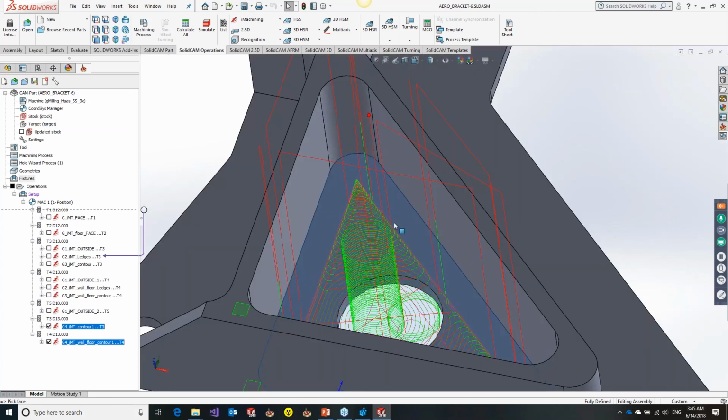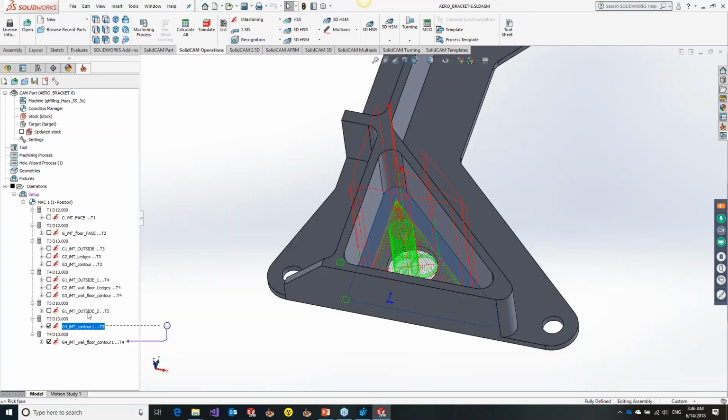We find the face, and we create the operations directly using that geometry. Definitely you need to watch Sid's webinar on this because he goes over all the ways it works, because you can drag and drop from over here. I don't want to give away the cool things that Sid does. But yeah, it's as simple as just holding Control, dragging it to a face, and you get your toolpath.